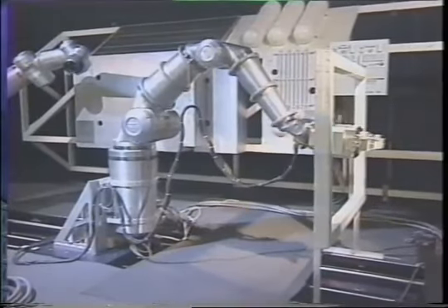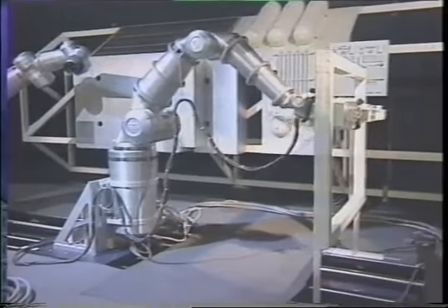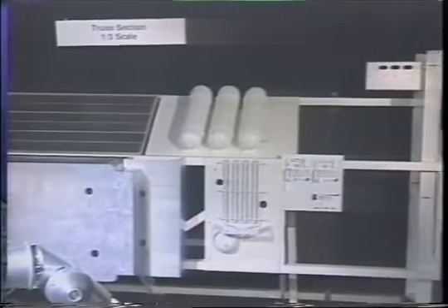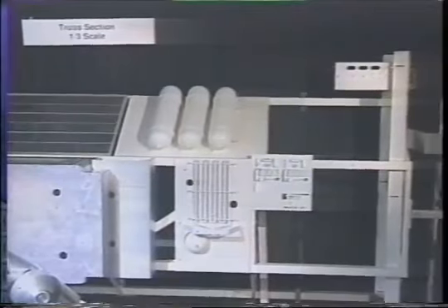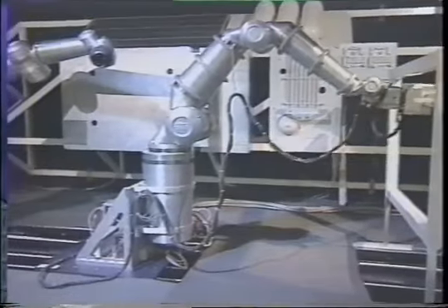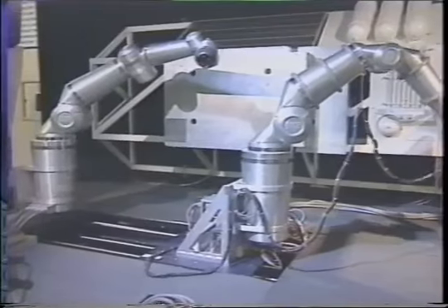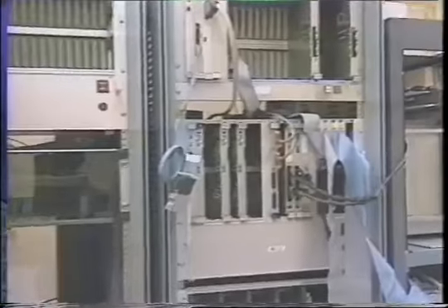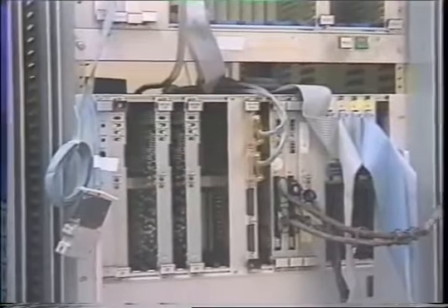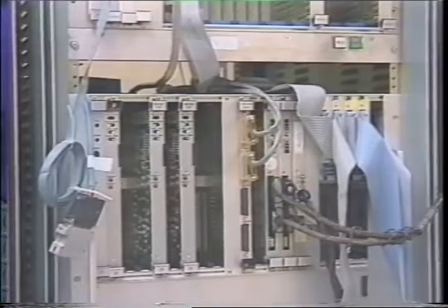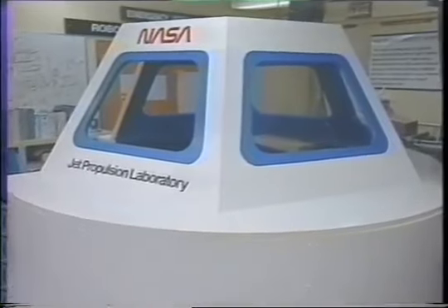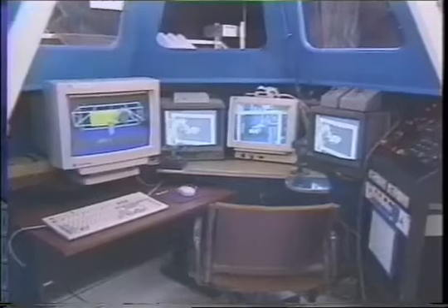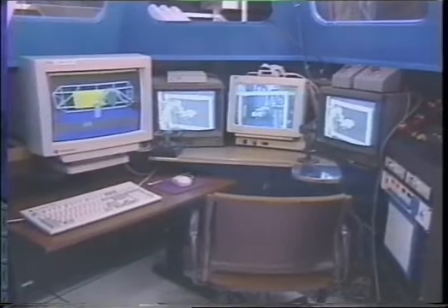The experimental facility, the JPL Remote Surface Inspection Laboratory, includes a 1/3 scale partial mock-up of the International Space Station, 2 Robotics Research Corporation dexterous 7 degree of freedom arms, a VxWorks VME arm control computer into which the obstacle detection and collision avoidance software is integrated, and an operator control station with video displays, joysticks, and a graphic workstation for simulations and user interface displays.